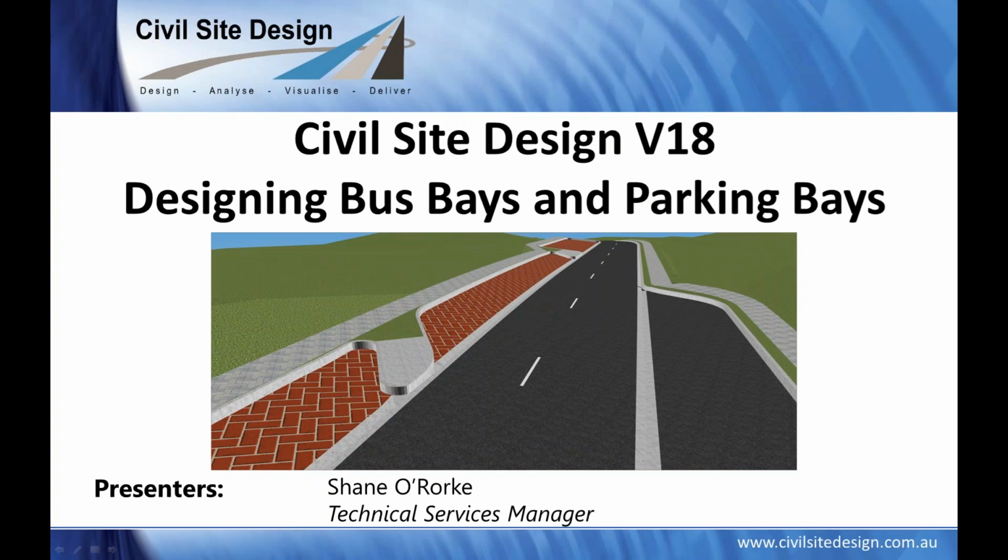We quite often get asked about designing bus bays and parking bays, and it's always an interesting discussion about what people want out of designing a bus bay and a parking bay. Are they looking to just extend out to some cross sections where the bay is wider? Do they want to independently design the edge of the bay? Is it a nice smooth entry and exit, like for a bus entry and exit into a side area? Or are we talking about 60-degree or 90-degree angle parking bays? And they all need a different treatment.